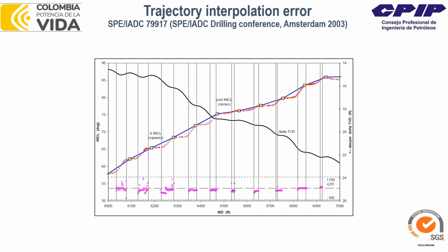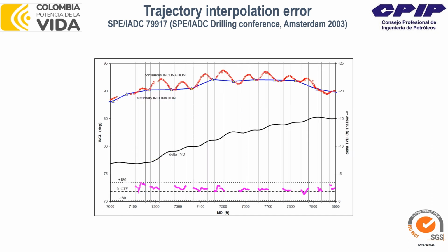So let's go next. This is the horizontal section. Now he tries to keep exactly 90 degrees. So what's going on here? If you let the BHA drill in rotary mode, it naturally drops the angle here. And what does the directional driller do? He builds up the angle just to keep it exactly at 90 degrees. And he does a good job, right?